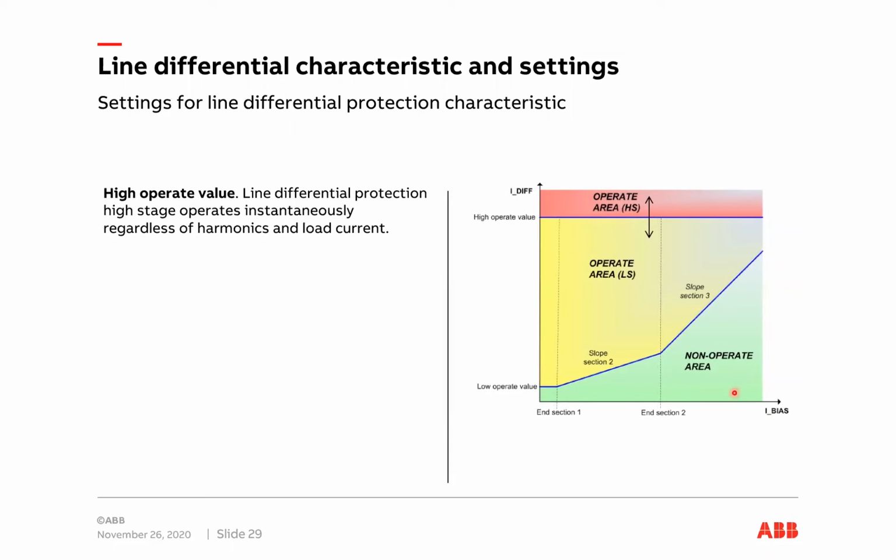And then we have the high operate value here as well. And it operates regardless of harmonics due to inrush current, or in case we are blocking the protection for other purposes. So it will always be on standby there.